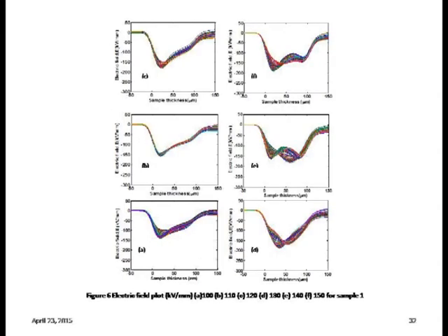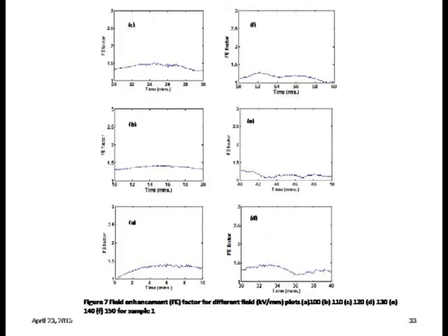So corresponding electric fields we have plotted, as I told you, otherwise that must be uniform, right? So this is a negative electric field actually. Ideally it should be uniform like this, but you can see clearly how distorted it is inside the insulation. So this peak field is around 150 kilovolt per mm, average may be around 100 kilovolt per mm. So that much enhancement in electric field is observed. This is the field enhancement factor.